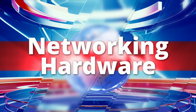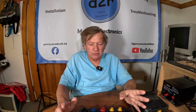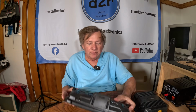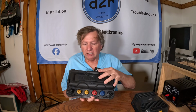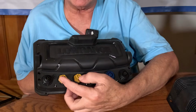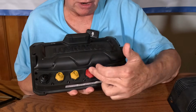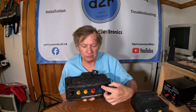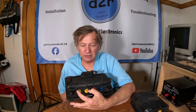All right, let's look at some hardware that's needed for both Ethernet and the NMEA 2000 buses. If you look on the back of your Lowrance units, okay, you'll see a lot of units will have 2 network Ethernet cables or connections. These are the yellow ones. And the little black one is the NMEA 2000 one. Power, and then you got the 2 transducers, okay? So we're just gonna deal with these over here, okay? So Ethernet is fairly simple.